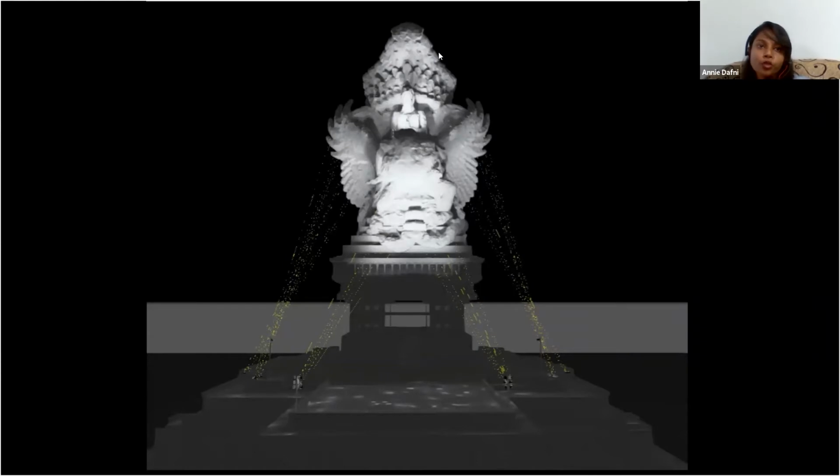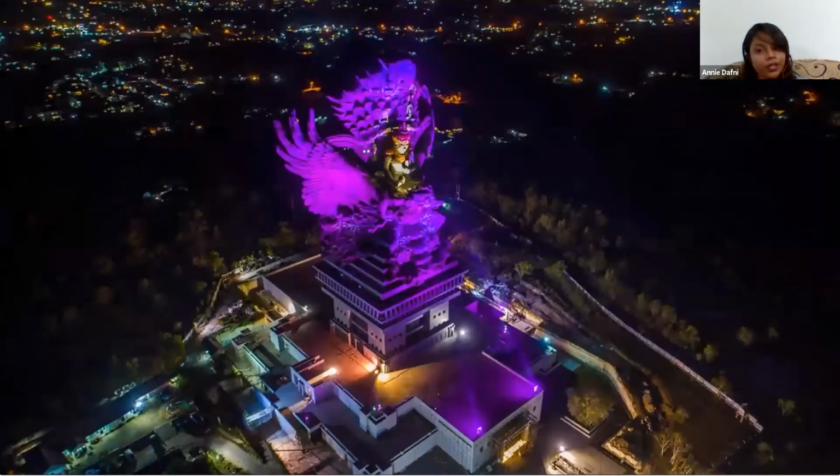But for the top portions, the medium beam might not be able to reach and give a good illumination level. So we've used the narrow or the no diffuser beams there, so that the light is able to reach those top portions and still give a good lux level. This is a Dialux simulated image, and this is a real image of the entire installation. And in addition, we also have some exterior projections for the wing to create animation effects here.